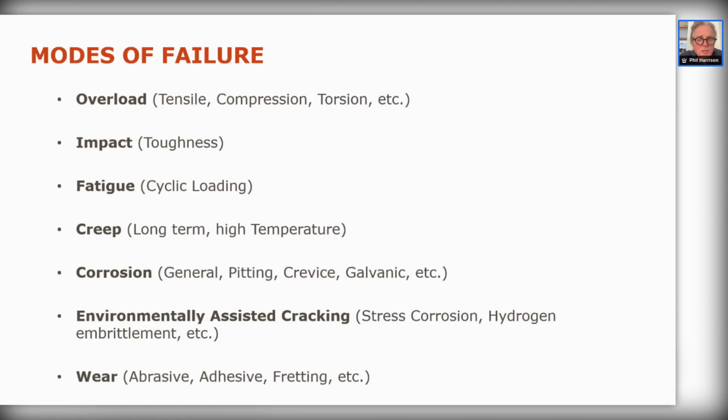You have to have a material which is susceptible to a specific corrodant in combination with a stress which is above a threshold level. For example, copper alloys and ammonia. You can just crack as a result of any internal stresses from fabrication of the material or built-up stresses through use of the material, which can result in failure of these.